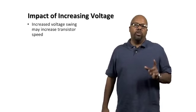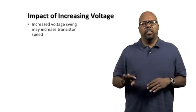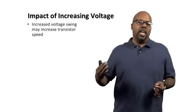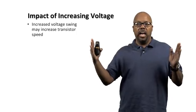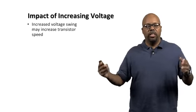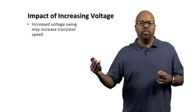So it may increase transistor speed because if the transistor is getting higher voltage, it can switch more quickly. Okay, so that's why it's done. And you have to do that. If you overclock, then, like I said, signals may not be able to reach the destination in time. So you have to increase the voltage in order to make them reach the destination in time. So that's why when you see your overclocking options, some of the higher overclocking options also increase the voltage.